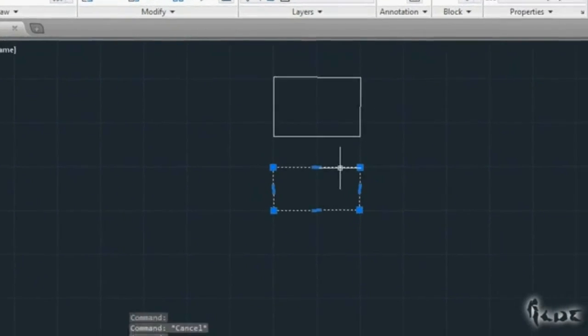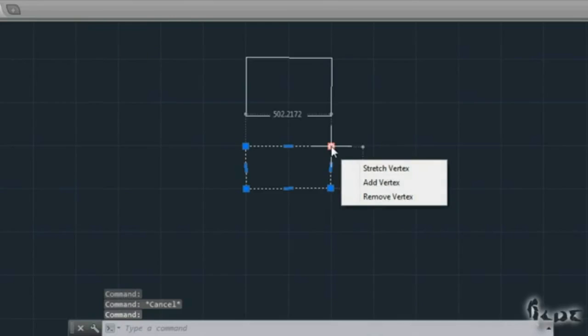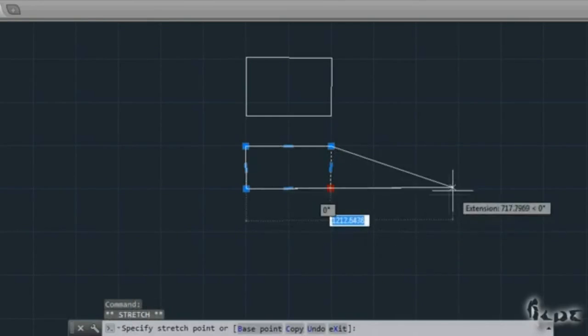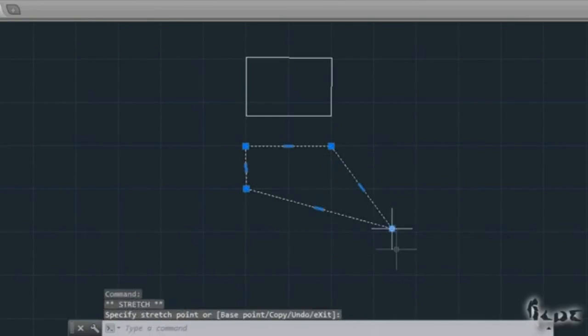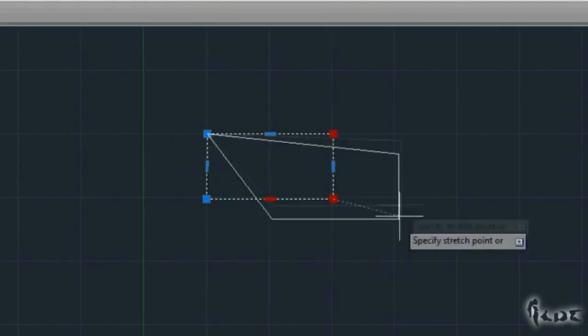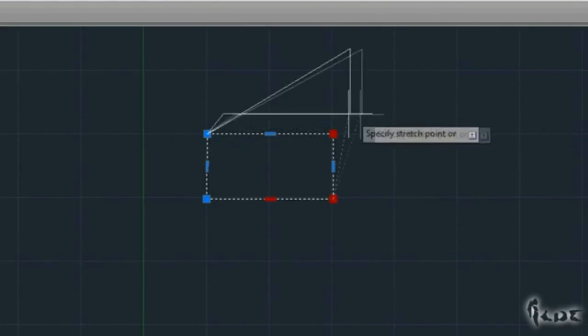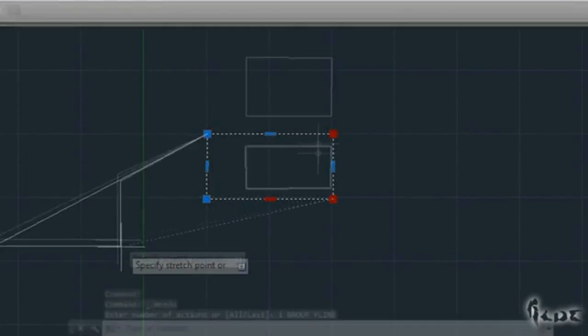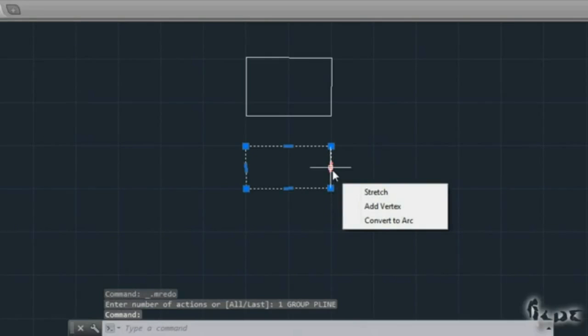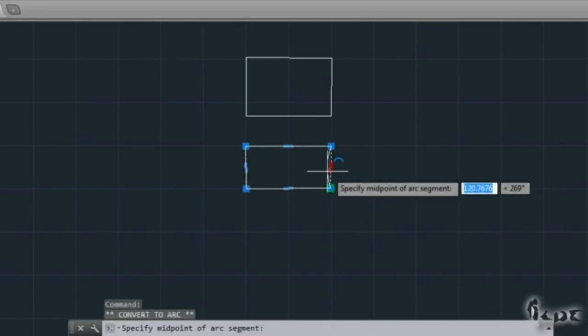Click on the polyline to start editing it. It will have square points and small rectangles on each side that you can use to edit your polyline properly. Hold Shift down to select more than one point to keep constant the sides that are between such points while editing. To make one of the straight lines curved, just hover for some time on the small rectangles until a list shows up. Go to Convert to Arc to start editing.